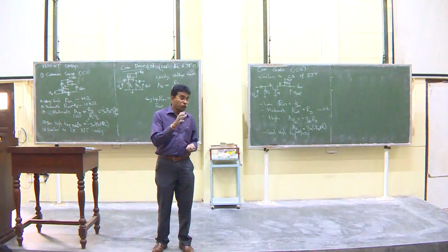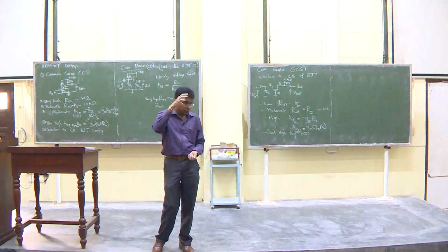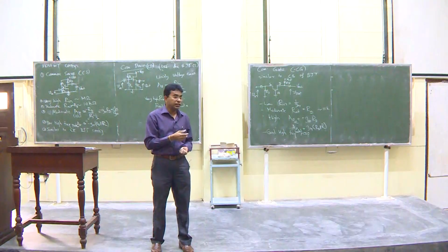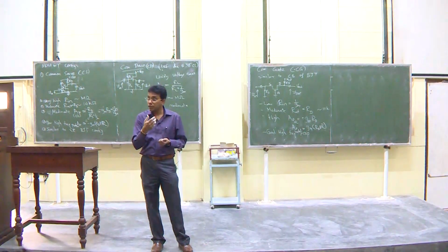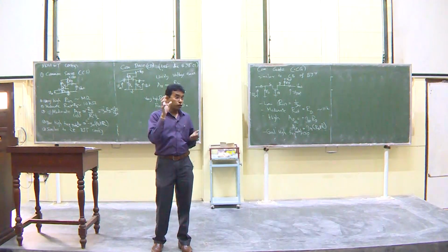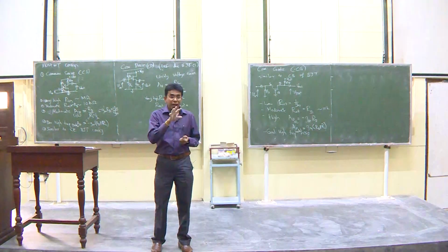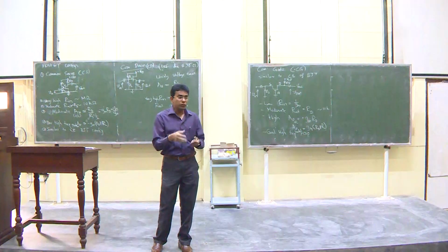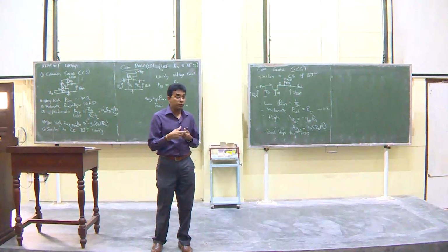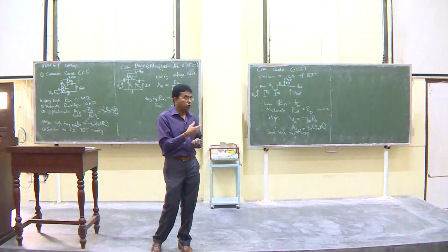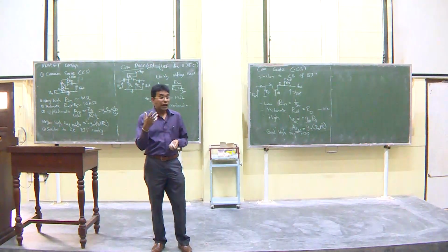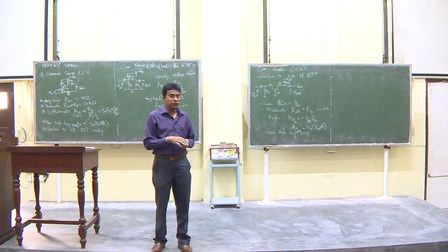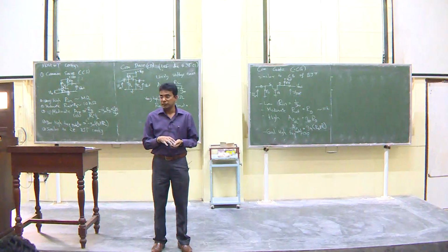But if you want to make high input impedance input stages, we use MOSFETs. That's why if you look inside an op-amp, these things will be used like input stages. There will be a MOSFET stage. Output will be a Darlington pair or some large current capable BJT circuit, right?